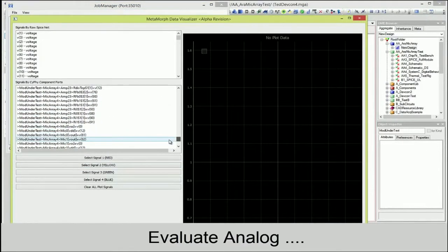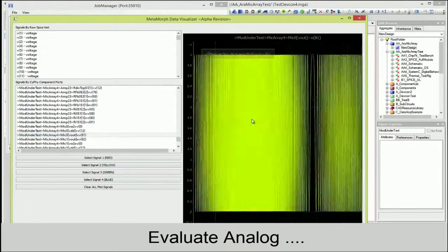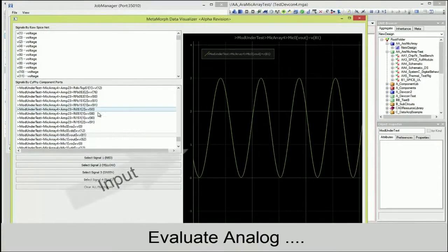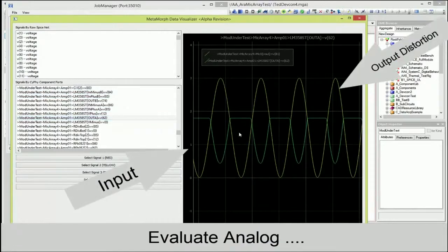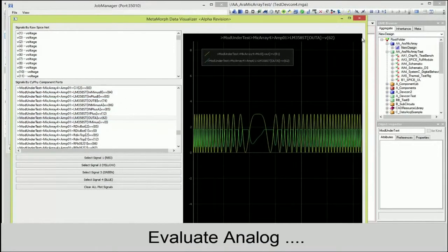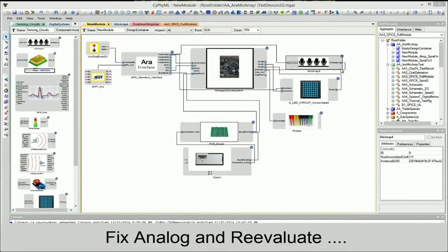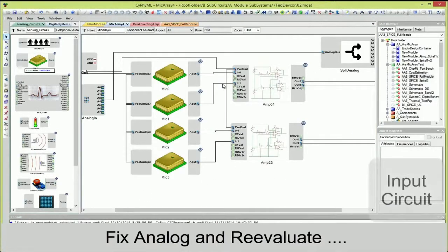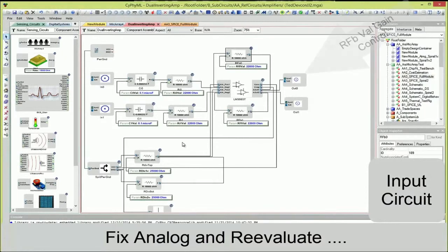So it ran the simulation. Let's go through the browser. We'll look at the output of the microphone. That's what's expected to generate a signal. We'll go through and look at the output of the amplifier. And oops, I have distortion. The headroom on my op amp's not big enough, chopping my signal. I don't want to build that, so let me go back, look at how it's implemented.